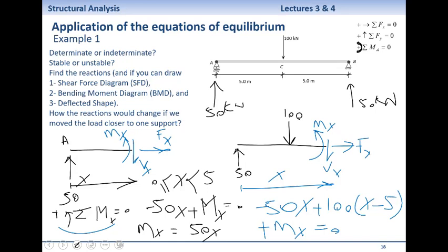It will, however, change your shear force value, and you will see that mathematically at that very point, it's a point of singularity. So you can't really determine the shear force, which doesn't matter physically. We don't really care about that one point. So we need to cut the beam twice to be able to complete that bending moment diagram.